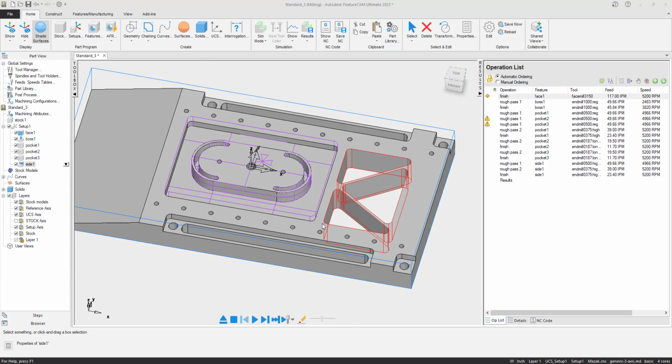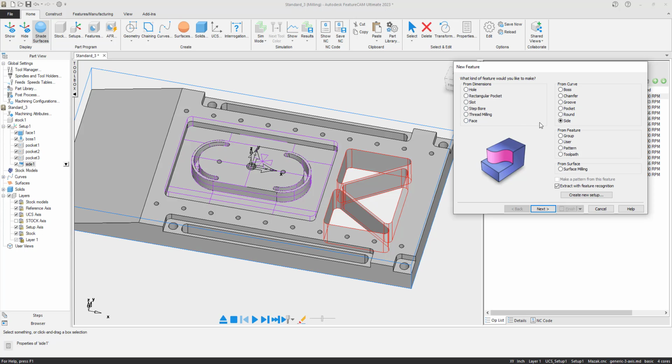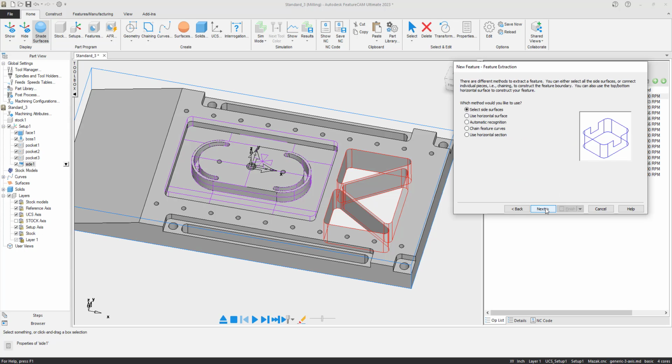The next thing we're going to look at, because I've already faced it, I've done these pockets and those pockets, and it has not taken us very long. What we're going to do next is we're going to select these open faces, and then we're going to go and select these pockets, and then we'll do the holes, and then we'll do some 3D surface milling. Okay, so let's go into features. I'm going to go into side. I'm going to click automatic feature recognition.